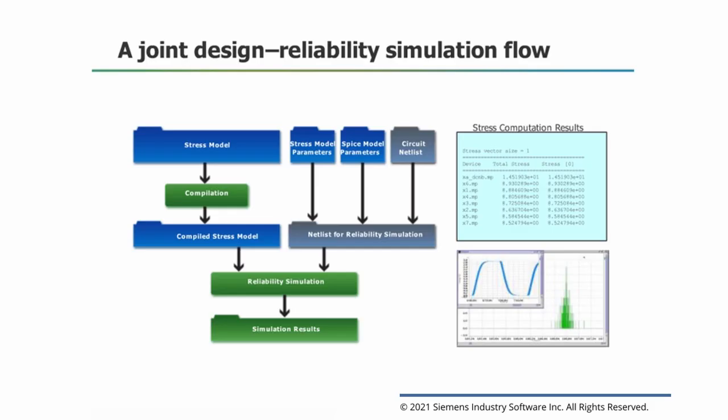The aging trajectories of two identical devices will be slightly different. That means devices that are matched at time zero may exhibit mismatch when they get old, with all the consequences on performance. Our simulators offer uniquely the possibility to assign statistical aging variations and simulate the resulting mismatch.